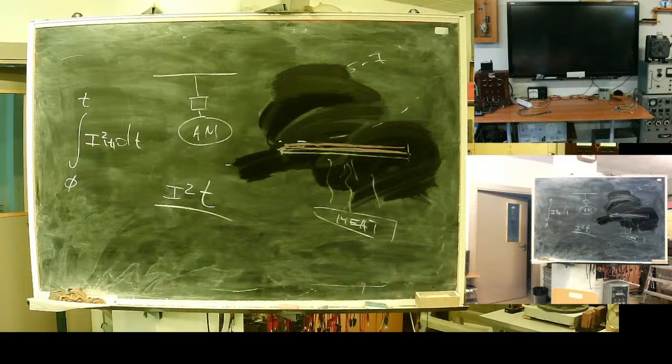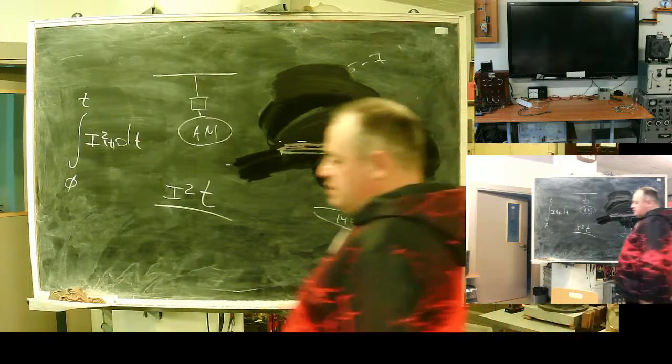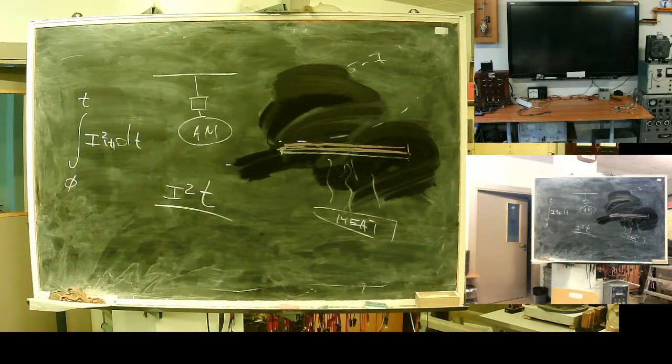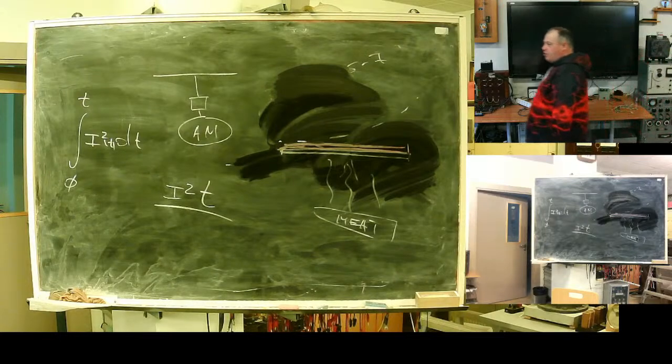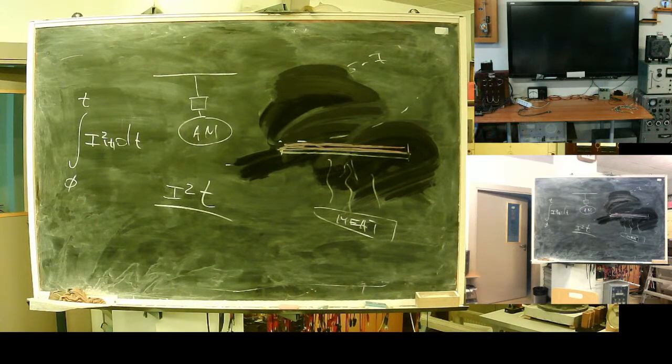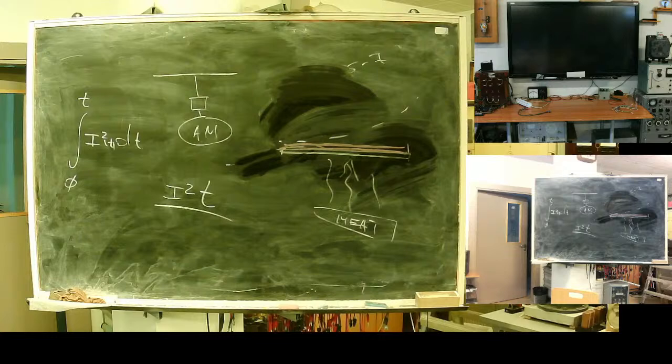But of course, it's good, but not so good. It's not precise. The problem with thermal relays is they are very imprecise. The trip current is dependent on ambient temperature, and that's not all. With time they lose their capacity and their characteristics. They are not the best solution.